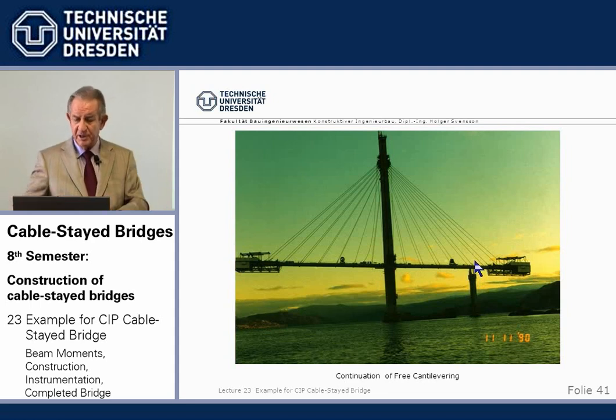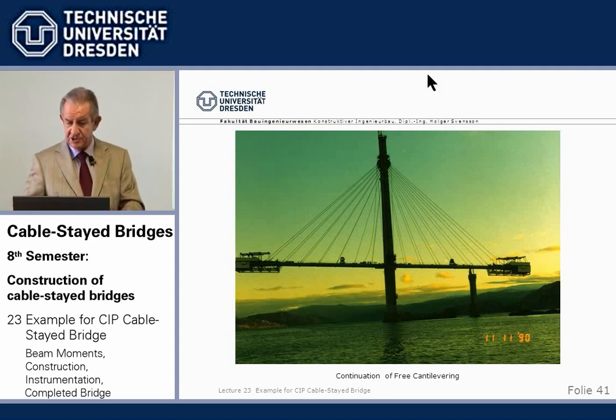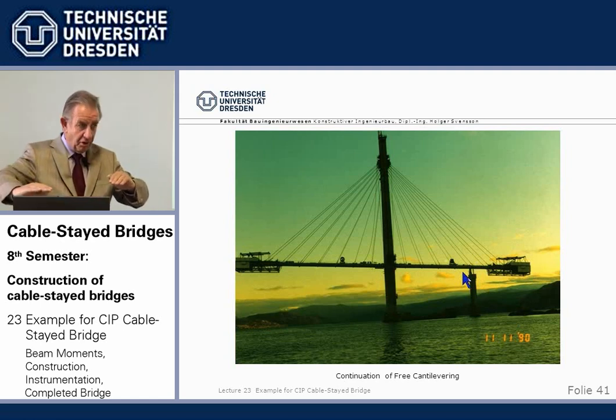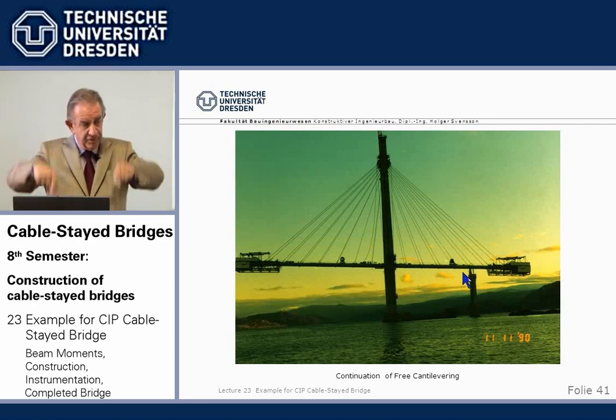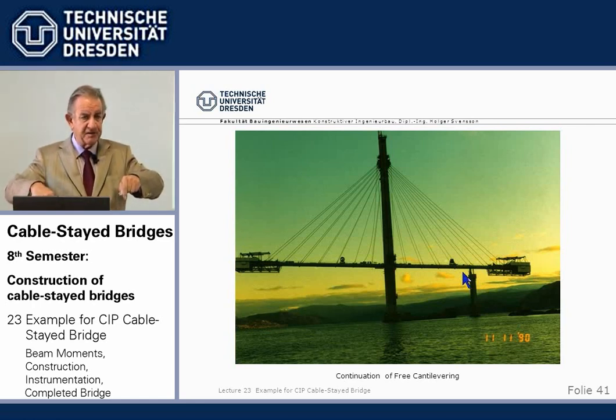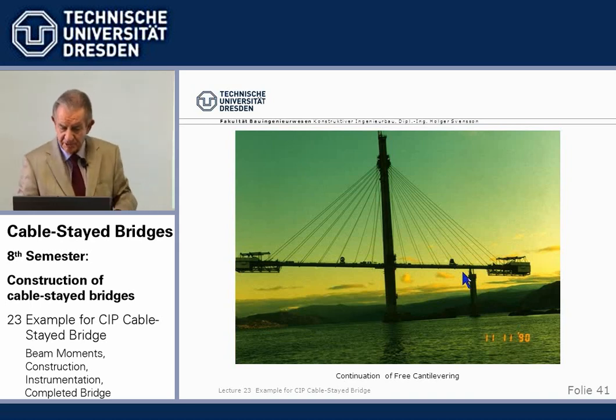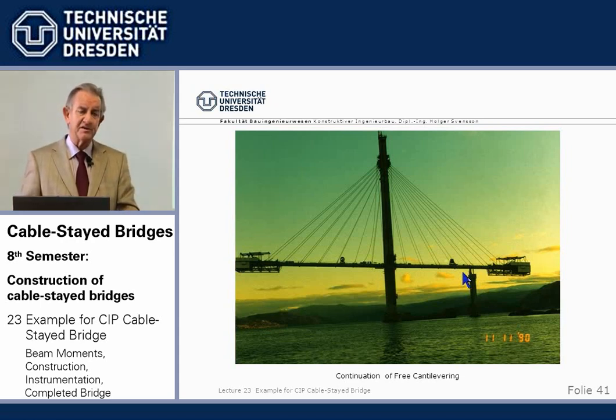So we had this auxiliary pier here which has a vertically sliding connection. So it takes only horizontal forces but not vertical, because otherwise we would have a hard spot in our elastic supports and we would have a kink of moments and all that. So that's where it was. At the end of construction it was detonated and served as a habitat for the fish.